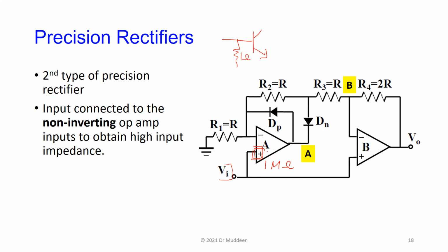So in general behavior, once you configure it for operation, the non-inverting input always has a higher input impedance than the inverting input. Why? Because in the inverting amplifier, we ground this input, and by doing so we make this point ground, so any input signal is going to see this resistor as the input impedance it has to feed, which is typically low. Okay, thank you very much, sir.